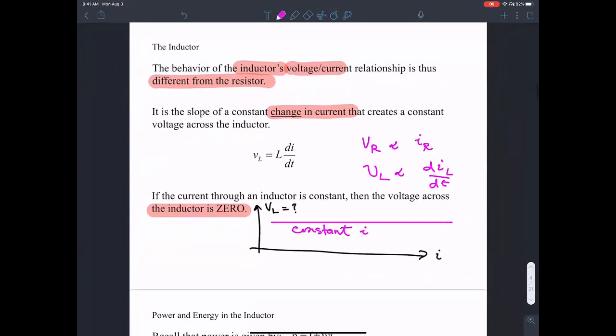So then you would need an AC current? Yes. To set up some voltage across inductance terminals, we need an AC current. Now, when a constant DC current is applied to an inductance, it acts as a short, meaning that there is no voltage drop across these terminals. It acts as a short circuit to DC.